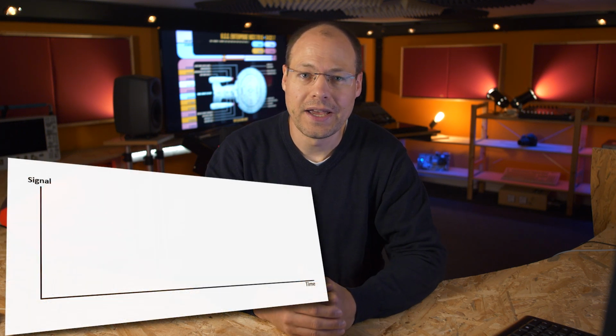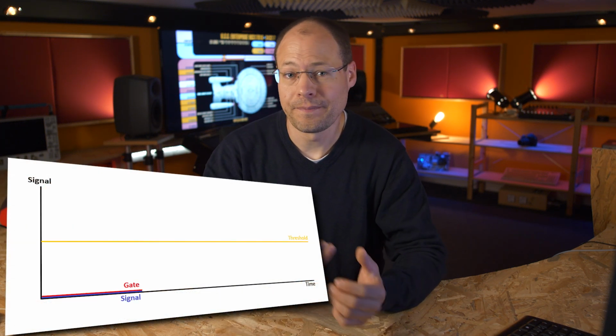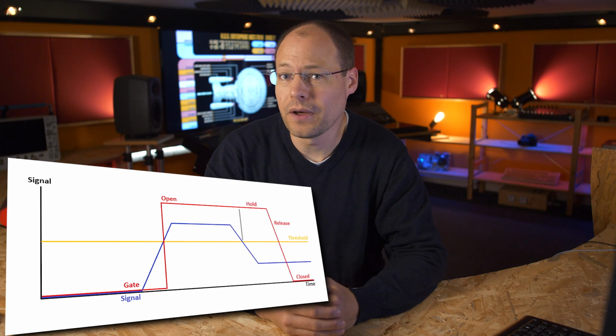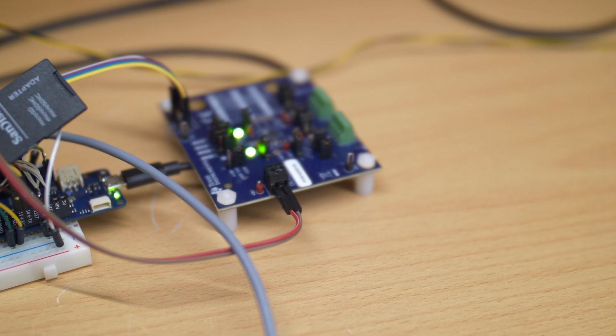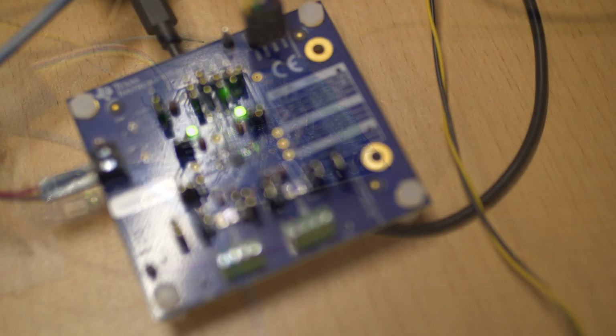Well, we have already achieved a lot and implemented a complete channel strip now. A noise gate can also be implemented as it is calculated almost identically to the audio compression. Only the division is no longer necessary, as we only have to open or close the gate when a threshold is exceeded, but no longer change the gain depending on the overshoot. This simplifies the calculation to a comparison with the threshold, the low-pass filter for gate open and gate close, and the multiplication.